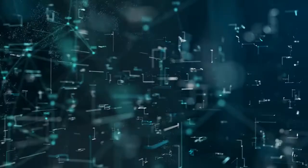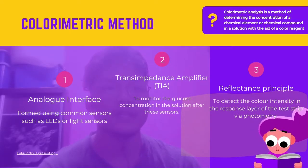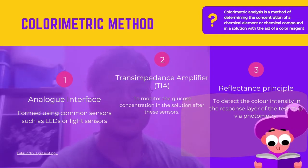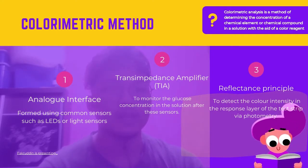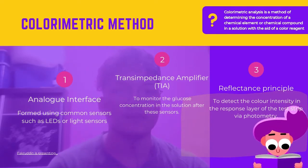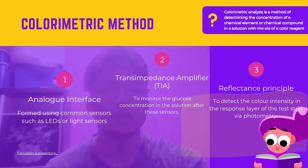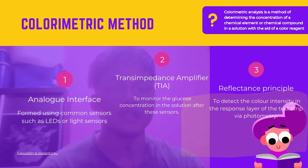A transimpedance amplifier, or TIA, is used to monitor the glucose concentration in the solution after the sensors. This approach employs the color reflection principle to detect the color intensity in the response layer of the test strip via photometry. A numerical value is generated by the glucose meter, which is a measurement of the glucose concentration in the solution.